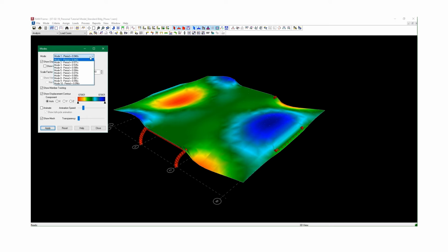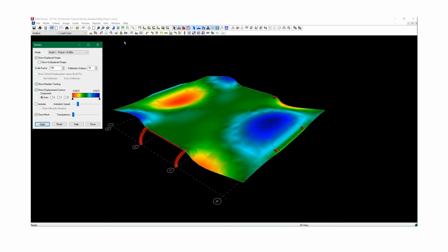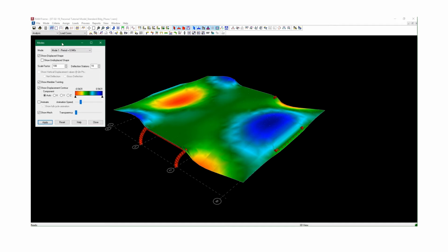The first mode, that's the natural period. The first mode oftentimes corresponds to the direction most likely to be unstable, in my mind, or where buckling would occur. If the structure starts to deflect and wants to bend over, it's probably going to take that first mode. Oftentimes, in my experience, that's been the case.